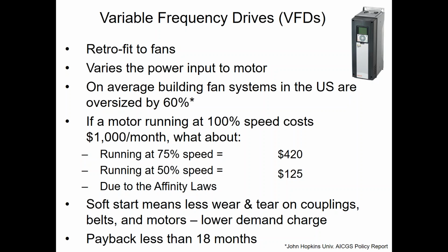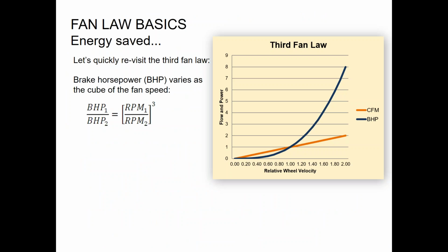And Pete chimes in on Scott's comment, asking if the fans were undersized or if there was too much duct leakage in the building. That's also pretty valid. Duct leakage is 25 to 35% for the average system. And that's how much air is getting lost out the duct system and going back into the plenum cavity, which is pretty bad. All right, I'm gonna keep on moving here.